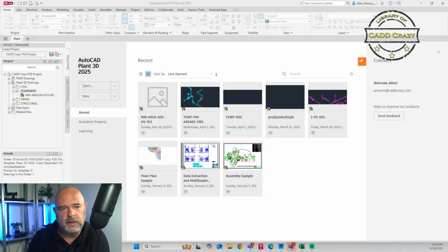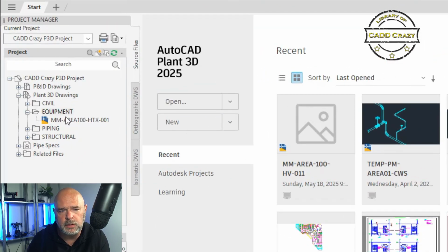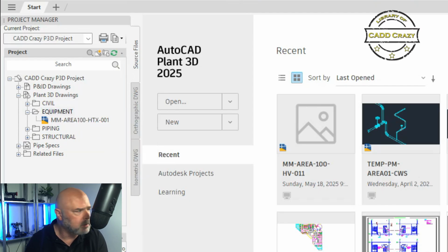So welcome back. We're going to be focusing on AutoCAD Plant 3D in this video, and in particular the equipment editor, or how to create equipment inside of your model. So basically what you're going to do, pretty simple, you're going to come over here and go to equipment. We have our folder structure and we have an equipment folder just for those models. We're going to right click on that one and say new drawing.